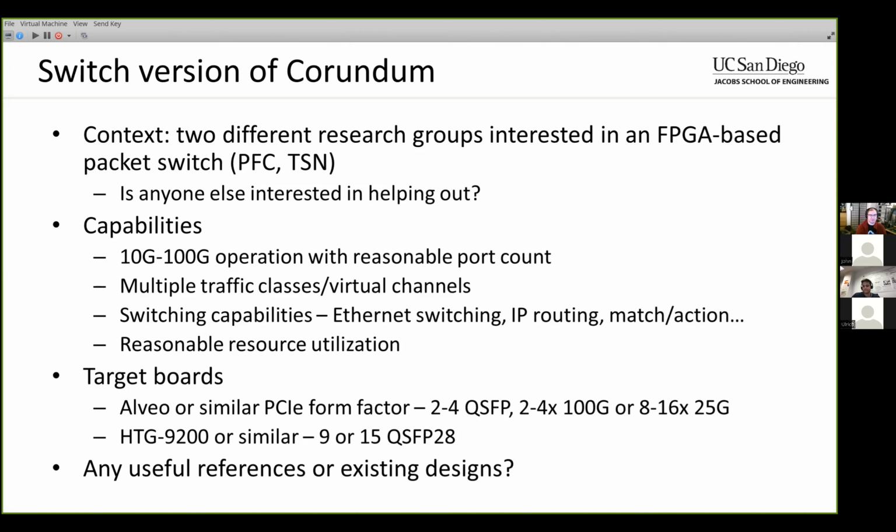Yeah, that's definitely a good thought as well. For research stuff, you can do things you normally wouldn't in terms of configuration. Because the routing decision component can definitely involve things like CAMs, which are not so great for implementing on FPGAs. I mean, they can certainly do it, and I know Xilinx has quite a bit of IP for implementing CAMs and whatnot. I've put together some Verilog for CAMs based on a couple of Xilinx white papers a while ago, but that's definitely going to require some thought.